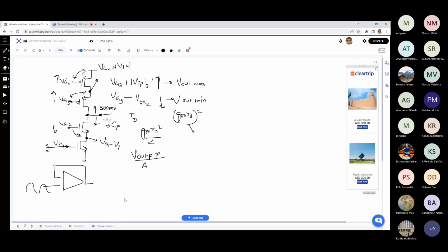So for that purpose, in differential amplifiers, a slightly different topology is also used that you will find in the textbook, which is called folded cascode. The concept is similar. Here, for example, the input device remains the same. First I will give you a simple cascode, and then we have folded. Folded means the PMOS is like this. It is called folded because the direction of the small signal current is folded. And here we put a current source. Suppose for the time being it is an ideal DC current source, I bias. Now Vout is being taken over here. This is constant VG2, some M2, and this is M1.